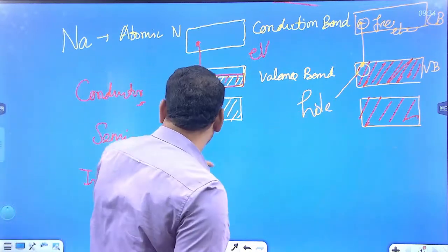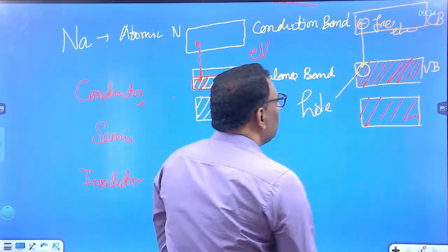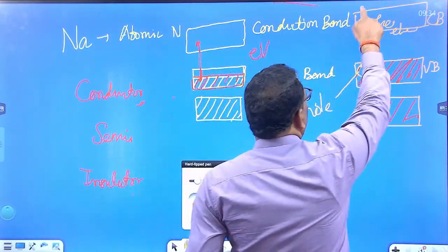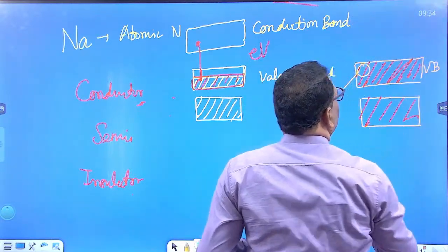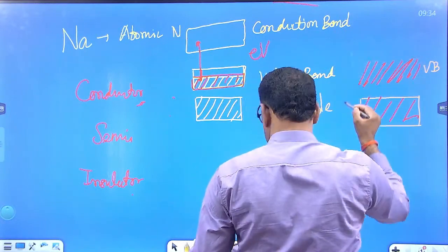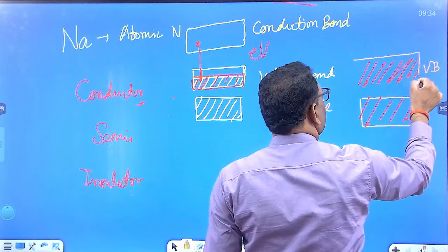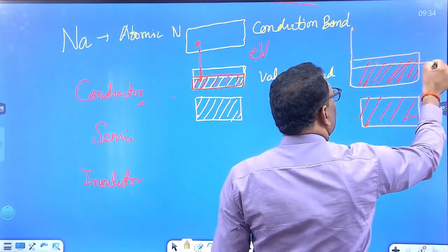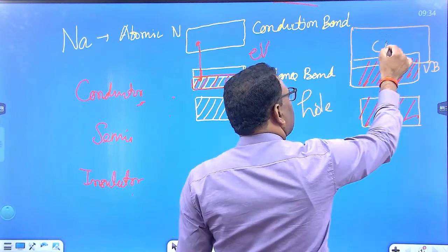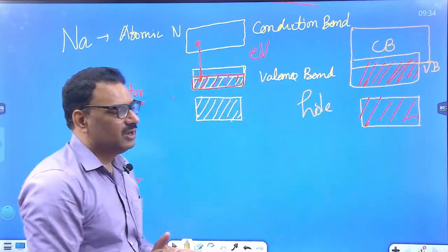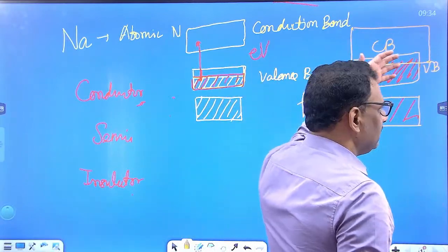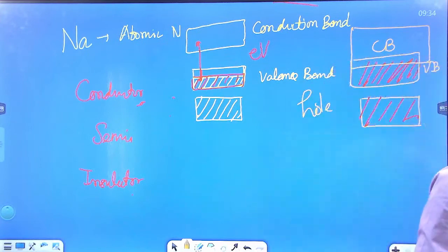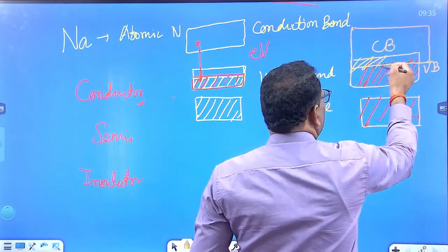तो जो आपका मेटल कंडक्टर है उसमें सिचुएशन जो होती है, इसमें जो कंडक्शन बैंड है आपका, this conduction band is overlapped. This conduction band and valence band will overlap. Means there is no requirement of external energy to make it free, because all the electrons are behaving as free electrons. So conductivity is very high because they are overlapping.